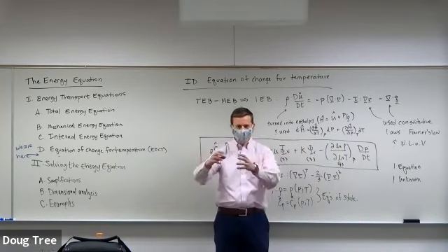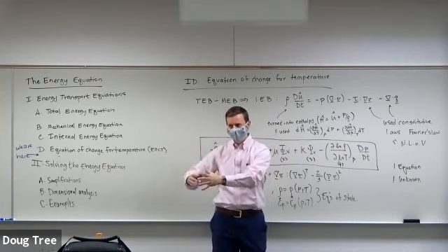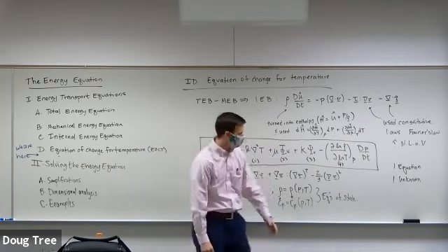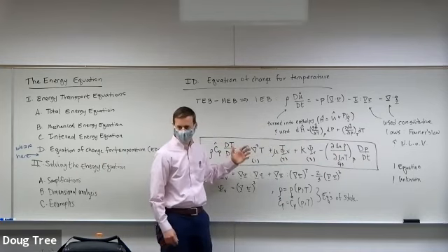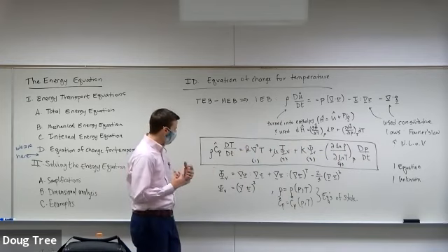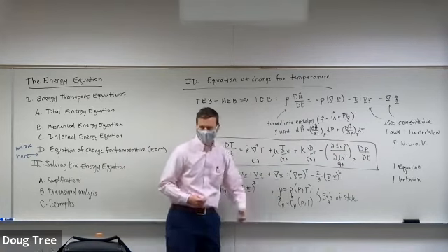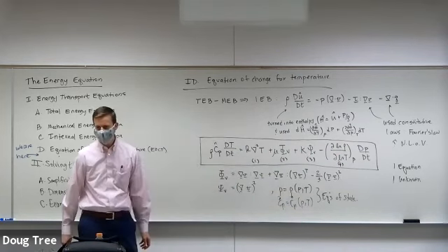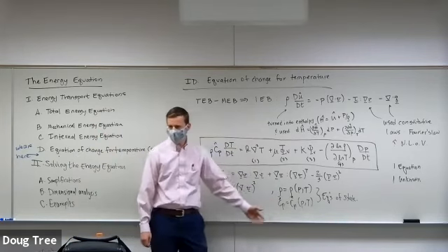Now we have some region in space where this might be happening. Over here, the temperature goes up or down because pressure is changing, and then we have to worry about how that's happening in space and time. So in order to really solve this, we need to know how the density relates to pressure and temperature, so we need the thermodynamic equation of state. And we need to know how the heat capacity changes with pressure and temperature.